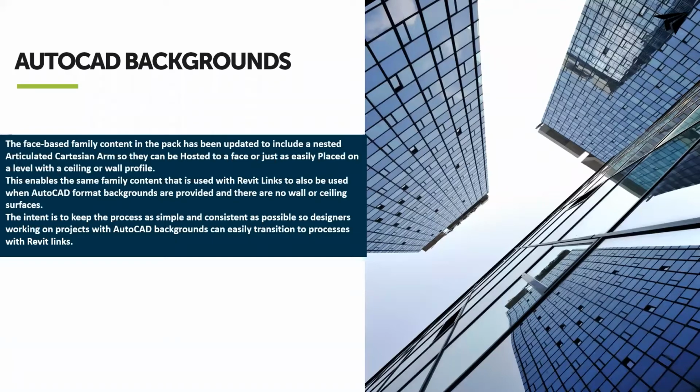So what we can do is bring in our MEP Productivity Pack families, and we can place those anywhere we'd like. We can select that line that's the wall in the AutoCAD background, and we can place it there level based, or work plane based, or reference plane based. It doesn't really matter. That's the whole point of that, and that's what it's good for. That way we can seamlessly work with an AutoCAD background if we have to, or you can work with a Revit background. It doesn't matter which one it is, we just get it done.